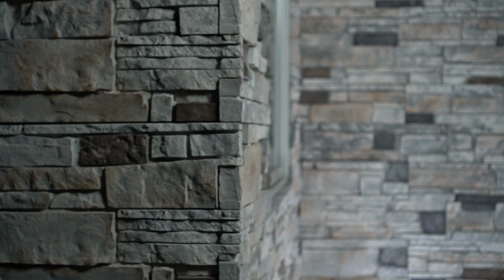Silvermine does not guarantee waterproofing when installing panels or sills in these situations, as keeping water from behind the Silvermine paneling is entirely dependent on how the trim has been installed and waterproofed. Silvermine's best recommendation in these situations includes trim flashing on second to last course under opening so flashing adjoins against the bottom edge of the opening.